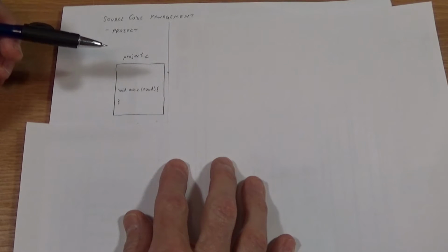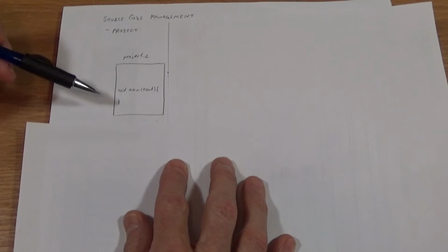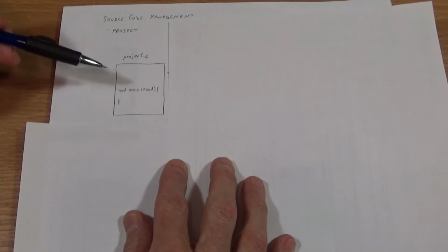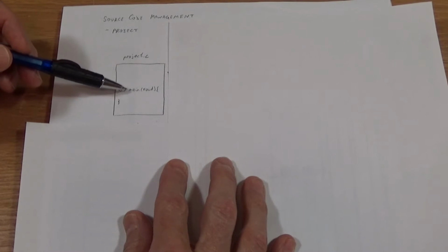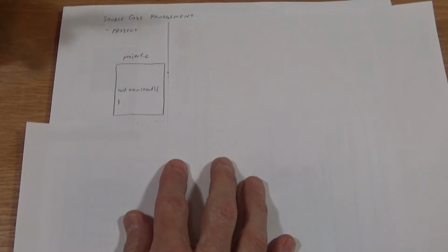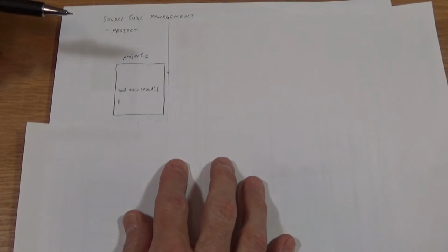If you dig around on your computer in the folder where Arduino is kept, you'll be able to find all these source files, and you'll eventually find one called main. In fact, in main it has two functions inside it: one function is called setup and the other function is called loop, which are the two functions that you have to write when you do your Arduino code. I'm not going to do it that way. We're going to do everything in main, and you're going to write your own main.